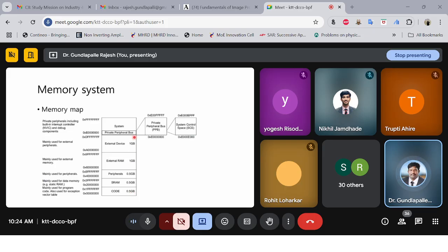The remaining 0.5 GB is exclusively used for the private peripherals, including the interrupt, and this is the nested vector interrupt controller. Out of this 0.5 GB, some is reserved for private peripheral buses, PPB and SCS.